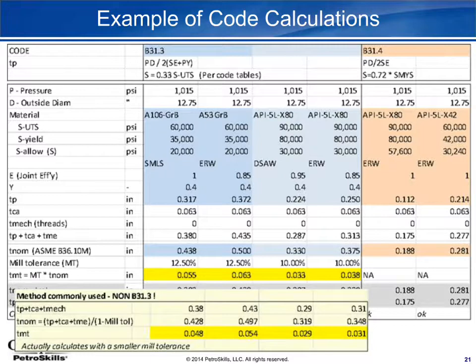If my design temperature for a piece of pipe is 120 degrees Fahrenheit, normal operating, and my construction is minus 40, unless I'm tied up against a major piece of process equipment or up against a piece of rotating equipment, there tends to be a lot of... we have to bear in mind there is hoop stress and longitudinal stresses, and in those longitudinal stresses there is a lot of headroom for allowing that thermal variation from construction.